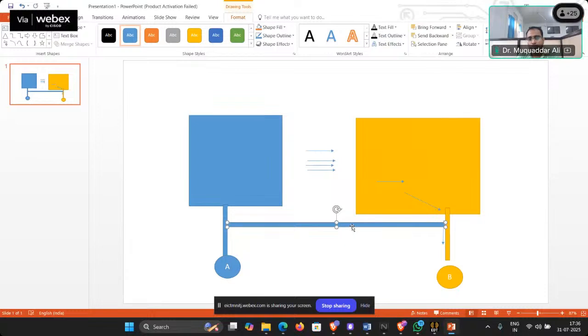if I can control the phase of this signal, and this 10% was coming at a 45-degree angle at this point, and this 10% is coming at 225-degree. So both of them are out of phase, so they will cancel out each other, right? So in that way, we can utilize this neutralization line and implement an isolation. Okay. So now we have just created a straight line.